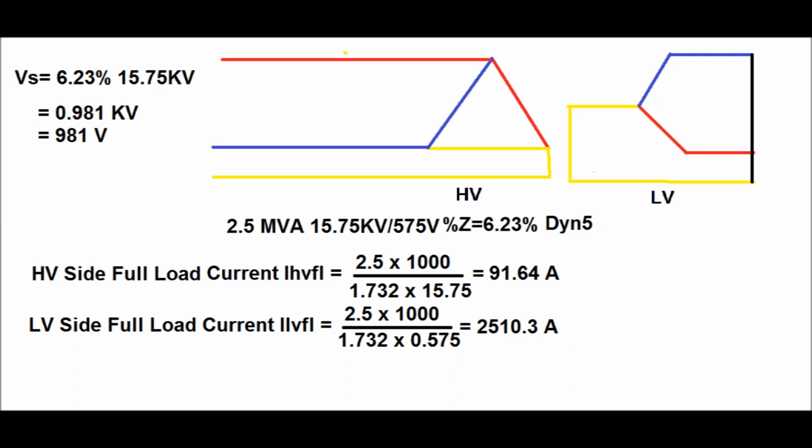The wattmeters connected to the secondary side of the CT and PT will show the total copper loss of the transformer of red phase, yellow phase and blue phase, as discussed earlier. Similarly, the total wattmeter reading should be multiplied by the multiplication factor of the CT ratio and the PT ratio used on the HV side to get the actual value of the copper loss in terms of the primary value.